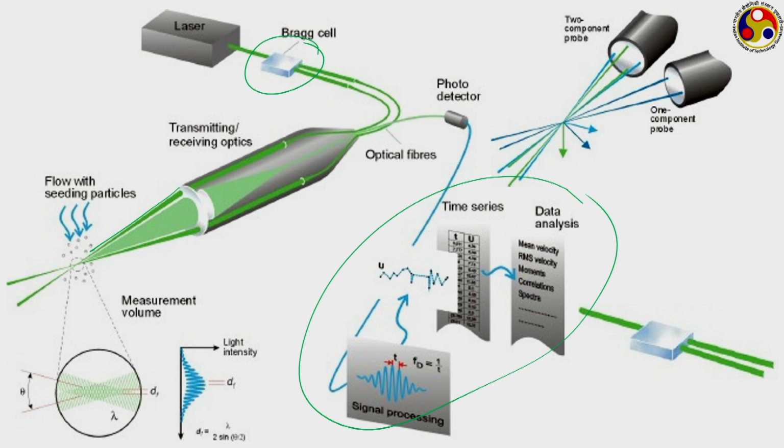are looking for two dimensional measurement, then we need two component probes just like this, which actually produces 4 beams and gives you 2 velocity components. And if we are looking for 3 dimensional measurement, then we combine a 2 component and 1 single component beam like the arrangement shown here, thereby resolving all the 3 velocity components.